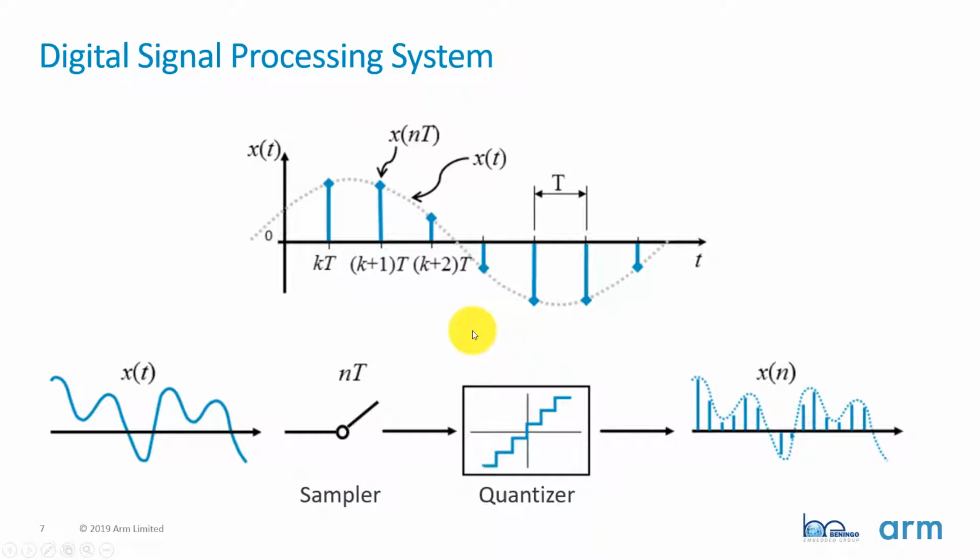And in order to sample that sensor inside the analog to digital converter, what we actually have here is some sampler. So we have our signal here, which is represented by some function x of t. We're going to have a sampler within our analog to digital converter, which is going to sample. We're going to have some quantizer within that allows us to provide an actual digital value.